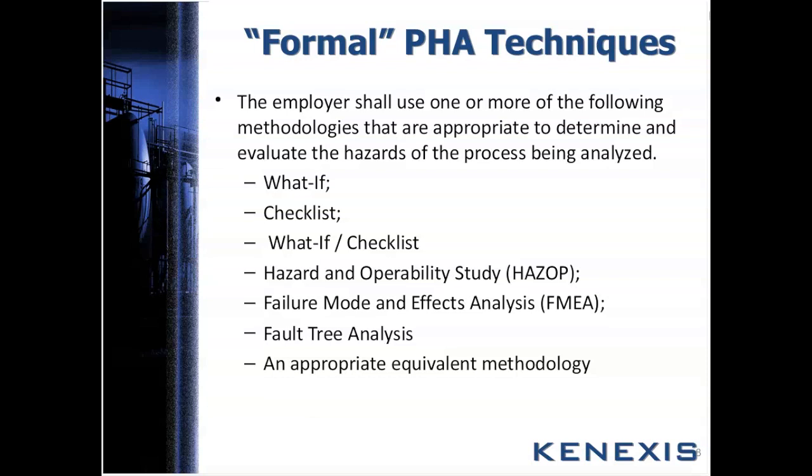They're efficient at taking a, you might say, broad brush look at the inherent hazards of a large plant or complex process. The other hazard evaluation techniques, such as the what-if checklist analysis, the HAZOP, and the FMEA, are excellent choices for performing a detailed analysis of a wide range of hazards during the design phase and during routine operation. A lot of times these studies will be followed up by more sophisticated techniques such as fault trees. We'll give a little bit more detail on those in a minute, okay?